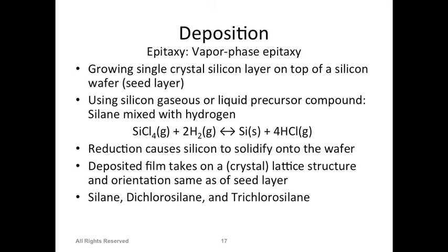And then you control the process conditions such that the deposited molecules will come at a certain ratio that they will start making structure. The new silicon will not just start depositing on the surface. The process will slow, and the new silicon atom will come and arrange itself on the surface such that it has a position so that it tries to fit in with the bottom crystal. In that way you actually grow crystal, not just any amorphous film. It's a CVD, but you grow crystal on the top.